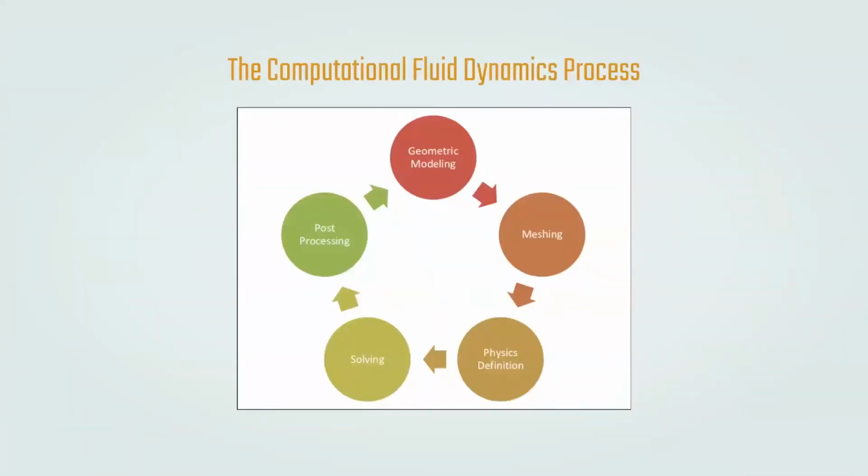In the computational fluid dynamics paradigm, there are several processes to keep in mind. The first one being modeling the geometry using computer-aided design. And then after we've done that, we can export the CAD file into the meshing software, where it is discretized or chopped up into multiple degrees of freedom. After that, we